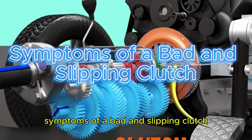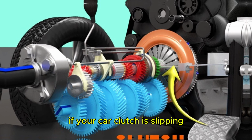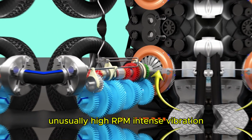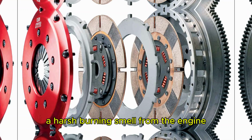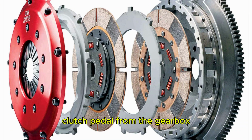Symptoms of a bad and slipping clutch. You will experience the following if your car clutch is slipping: grinding sound, difficulty changing gears, unusually high RPM, intense vibration, a harsh burning smell from the engine, clutch feels soft or spongy when pressed, and stuck clutch pedal.